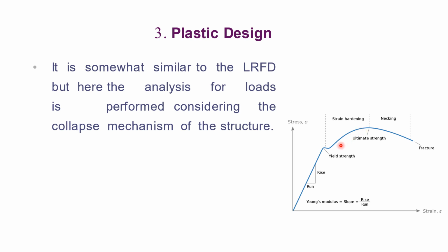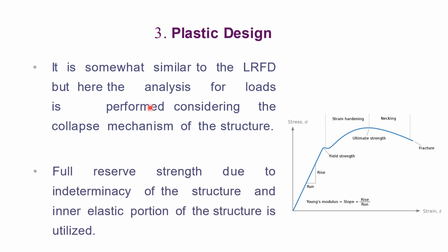The ultimate strength means the steel member can still take load from this region. So to get this benefit in the design, this design methodology is called plastic design. After the yield point there are permanent deformations, or the other name, plastic deformation. That's why in this range the design is called plastic design.